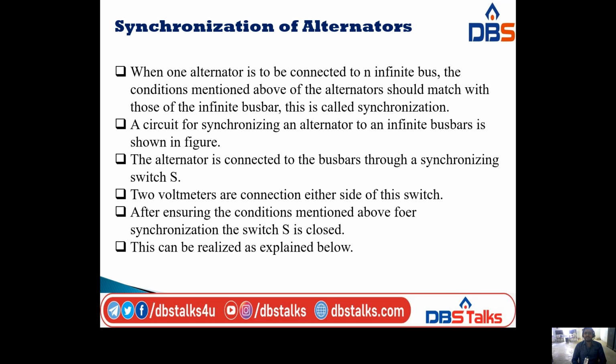Next, when one alternator is to be connected to an infinite bus, the three conditions mentioned above should match those of the infinite bus bar. Those conditions will have to satisfy the infinite bus bar conditions also. That means both should match. So one alternator is to be connected to an infinite bus. The conditions of the alternator should match the infinite bus bar conditions. Then it is called